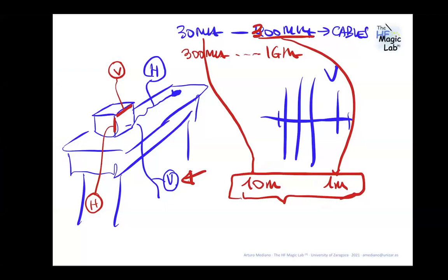For a switching low side MOSFET of a boost converter where there's a shunt resistor to measure overcurrent from source to GND, where should the RC snubber be connected? From the switching node drain to GND, or between the drain and the source? In my opinion, it's from the drain to the source, but I cannot answer this question totally sure about that. No. Okay.